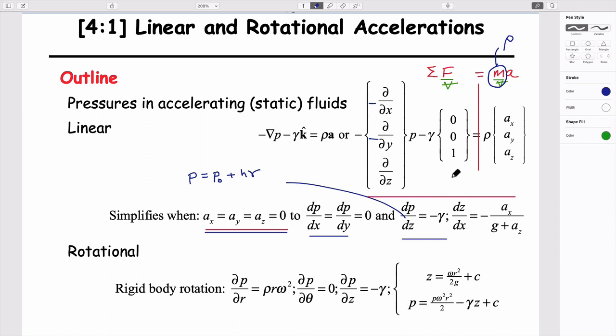By definition, since we can make this right-hand term look the same as these here, these have to be the same units as this dP/dz term. And so we can think of this change in pressure with elevation, this differential, just as a force per unit volume, because that's exactly what the units are here.